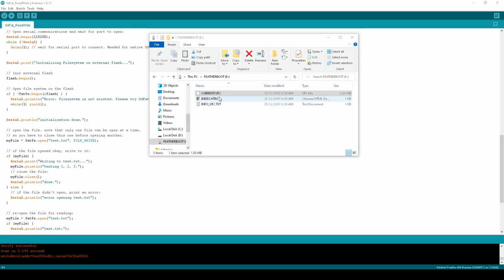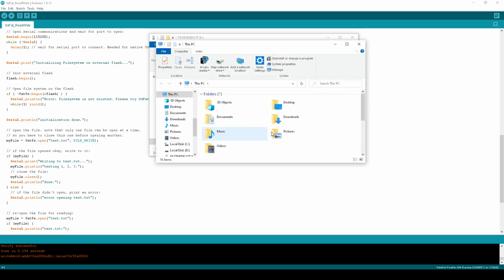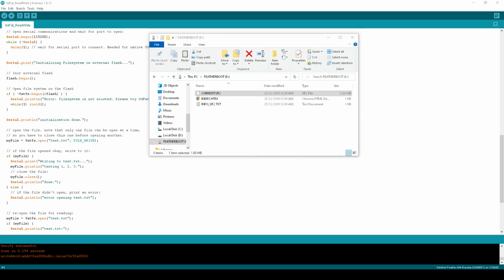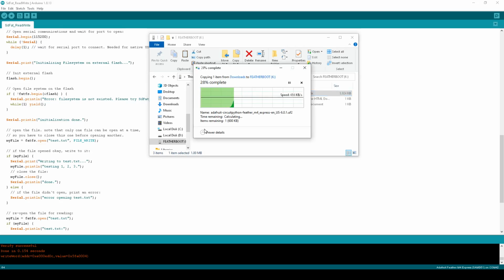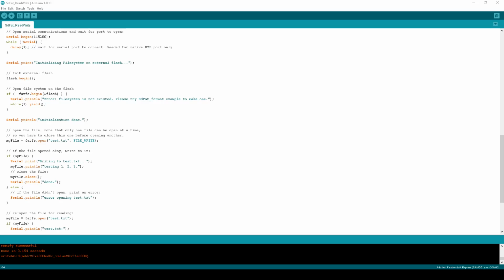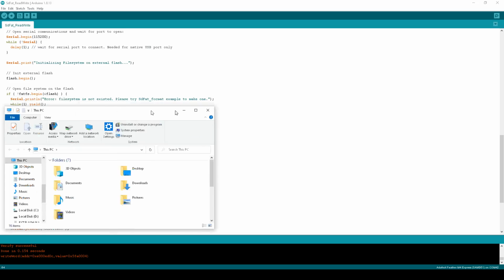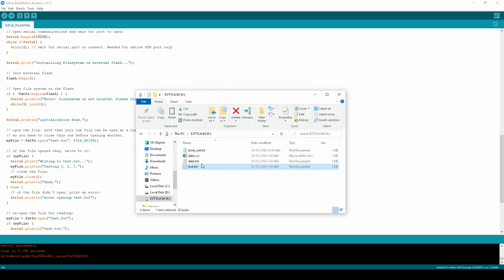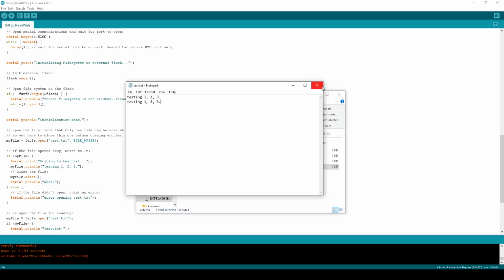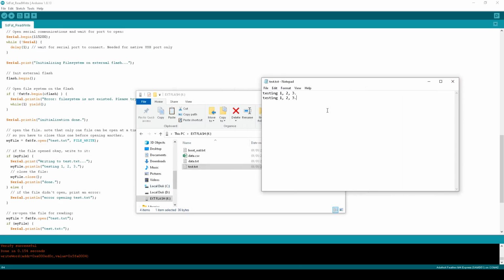Now I'm going to upload CircuitPython to view the data. It's just a convenient way to expose the flash storage rather than uploading another Arduino file. That exposes the flash, and we know that test.txt has been written, right? Now I could add configuration data. Let's say the ADC has an offset of 1024 and a gain of, say, 55. You press save, and you've saved it onto the flash storage.